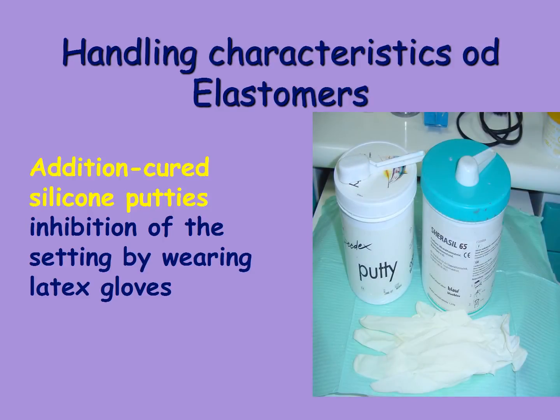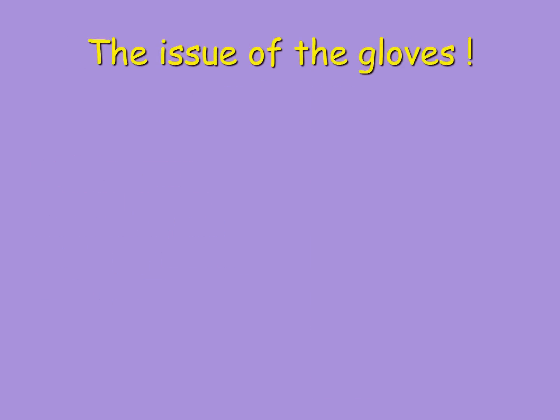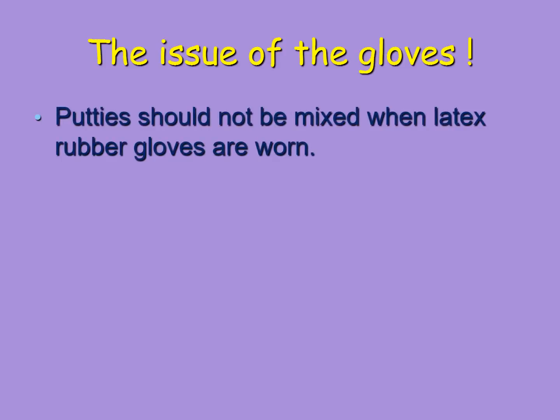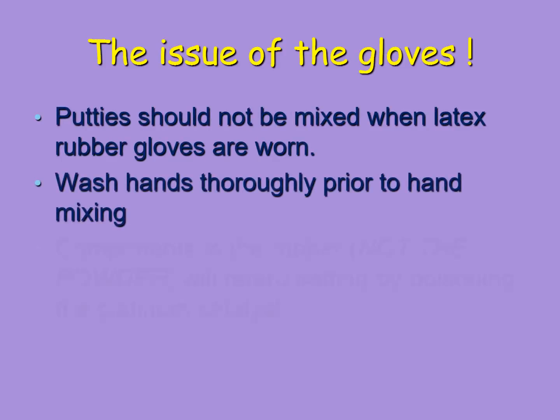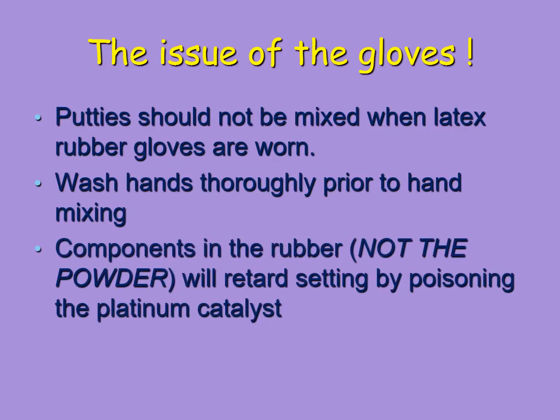Wearing latex gloves will inhibit the setting of addition cured silicone putties. Putties should not be mixed when latex rubber gloves are worn. Wash hands thoroughly prior to hand mixing. Components in the rubber, not the powder, will retard setting by poisoning the platinum catalyst.